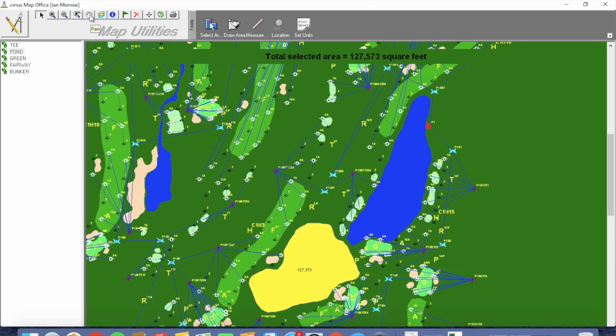And from watering the whole course for 15 minutes on a dry run, we see that the course uses 419,000 US gallons of water a night. So by taking that and dividing it into the 19 million, we have 45 days of water available if there was no recharge.